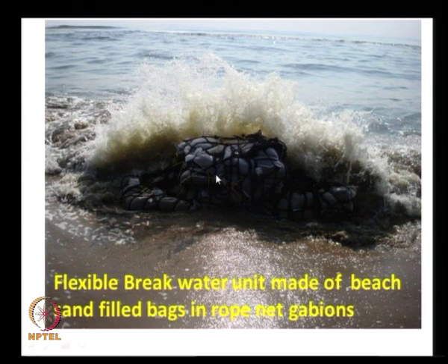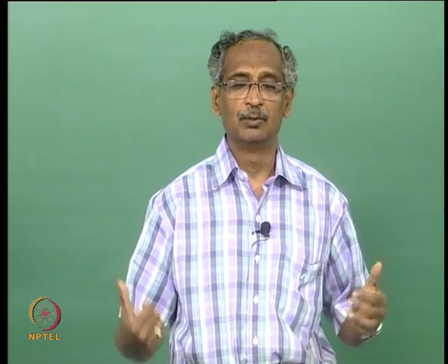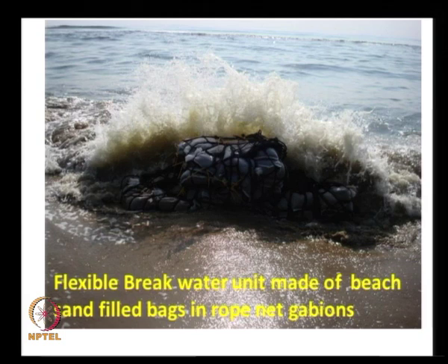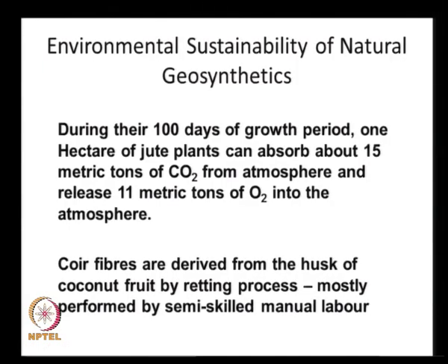If it were not for beach sand, we would need to import large boulders, and that is the typical solution adopted at most of the Indian coastal protection systems. We just simply bring the large boulders and dump them to counteract the erosive forces. But here we can use the abundantly available local beach sand itself to construct our structures, and this is one application that is sustainable, because we are not really destroying any natural resources in this construction.